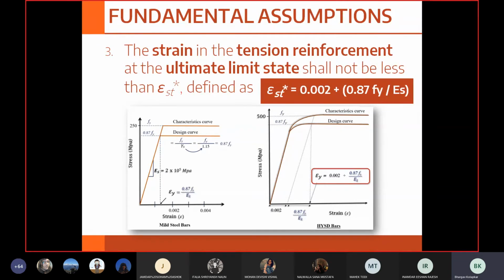When the strain in concrete is 5, the strain in steel should be 25. You start loading it further, steel can take up to 100, but at 50 itself, the entire member will collapse. So there is no point in defining an upper limit for steel because the member is not going to deflect that much in any way, it will collapse.